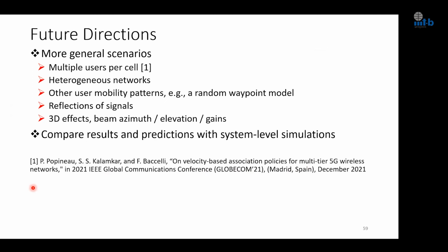Yeah, something of that sort. Primarily my point was that the frequency of operation eventually defines the number of beams that are required. As you go to higher frequencies, due to the path loss factors, probably you have to put in narrow beams to cover the area.